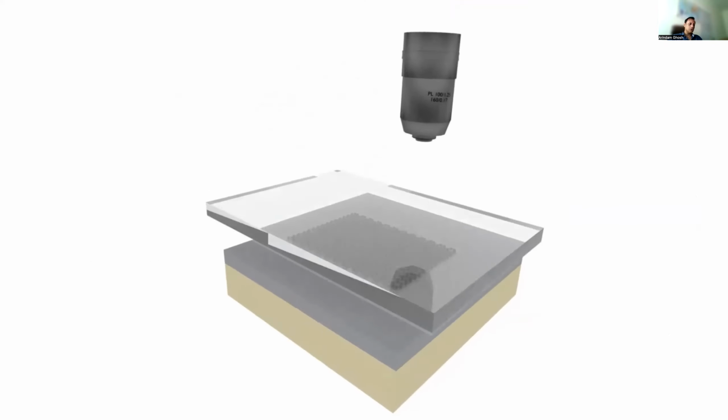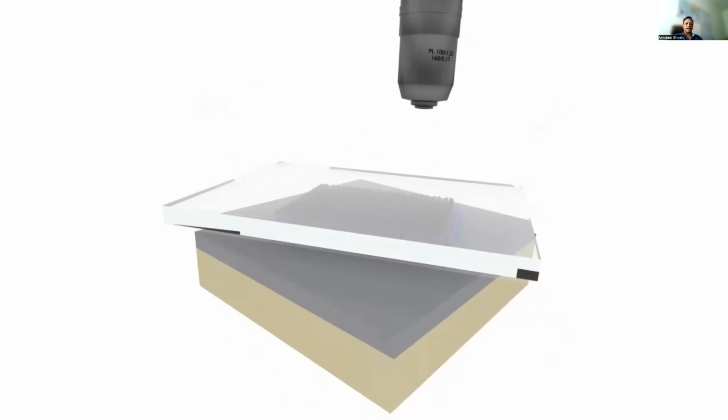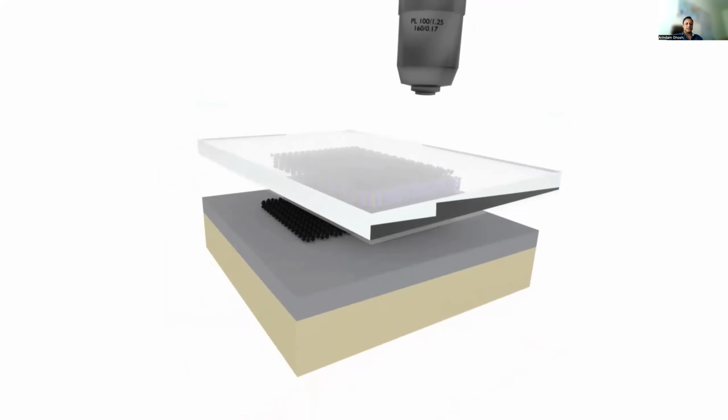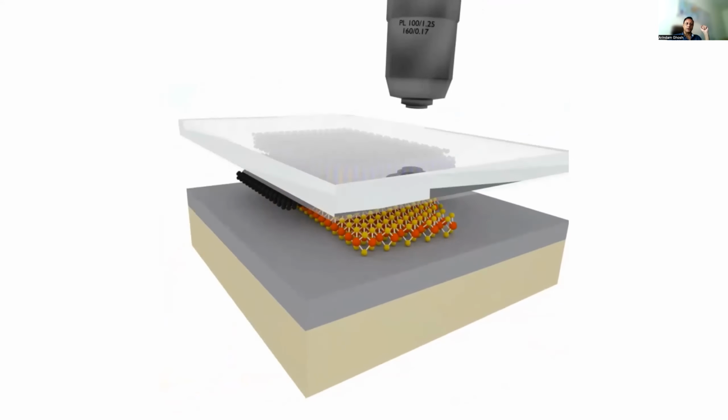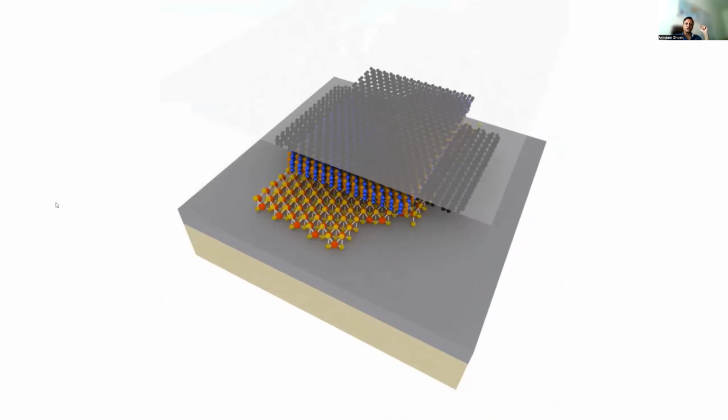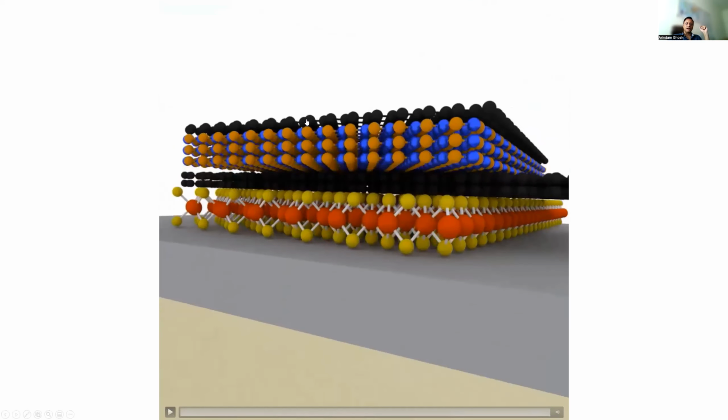The van der Waals structures themselves, this is a common video that I always show. I'm sure many of you have seen this already, but typically this is how we create the heterostructure. We use one layer to pick up the next one. This is a typical example, although this is one of the relevant examples today because we use this particular structure for single photon detection in van der Waals structures. This structure has graphene on top. It has boron nitride underneath, and then a bilayer graphene and a chalcogenide layer at the bottom. So you can do whatever you want.